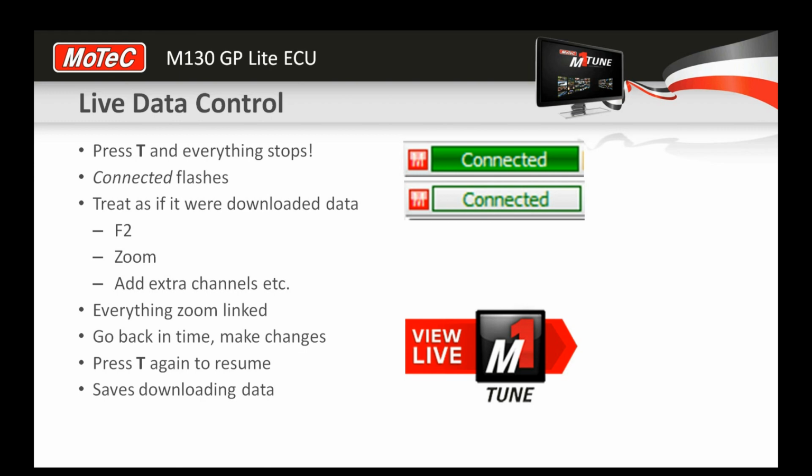So when we do that, I'll show you shortly live, the connected bar flashes to show you that you are paused, and then effectively it's almost exactly the same as using data in our I2 analysis software. So we can go back in time, sometimes up to 20 minutes or so, and have a look at information: what the Lambda was, did we have an error, did it overboost. So you're instantly looking at log data, and you can then make changes based on that.